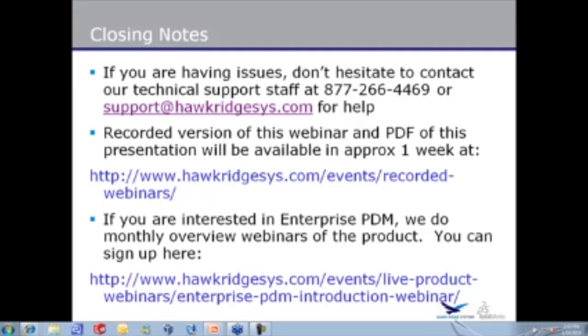In the future, will there be a dumbed-down version of Enterprise that could replace PDM Workgroup? That's a good question, Jeremiah. I don't know. There may be, there may not be. SOLIDWORKS certainly has not divulged any of those plans to me. If I find out, I can let you guys know, but right now I don't know the answer to that question. Does Enterprise PDM use SQL? Yes, it does. It supports SQL 2005 or 2008 right now, and it actually comes with Enterprise, so you don't have to buy SQL if you get Enterprise.